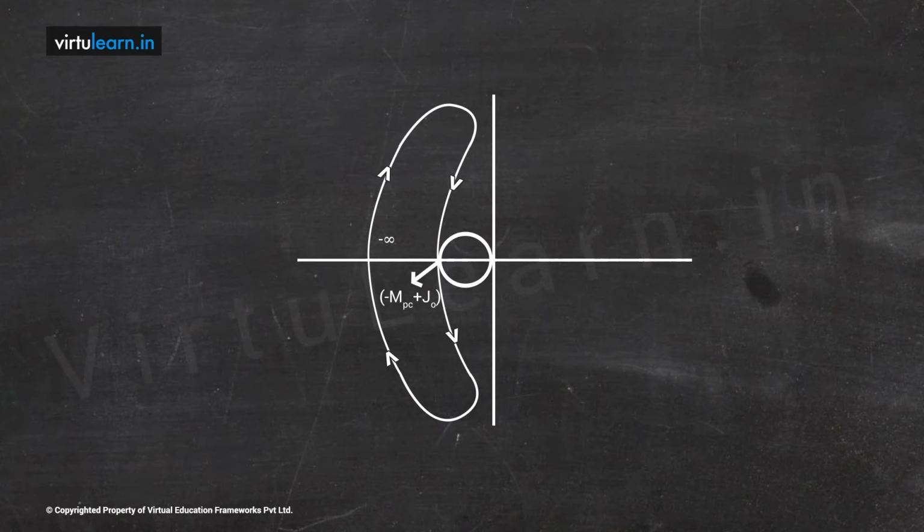And when you take the C point, it is a clockwise direction. So 1 clockwise and 2 anti-clockwise. So anti-clockwise is 1 and clockwise is minus 1. The result will be N is equal to 1. So when N is 1, as a result we can say there is only one encirclement in the anti-clockwise direction.